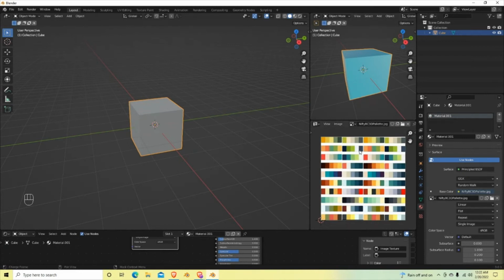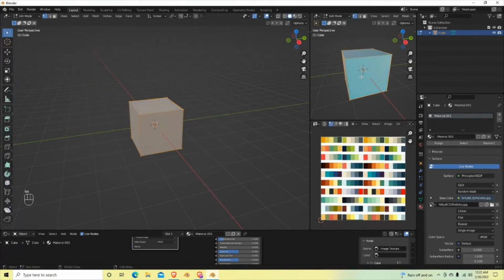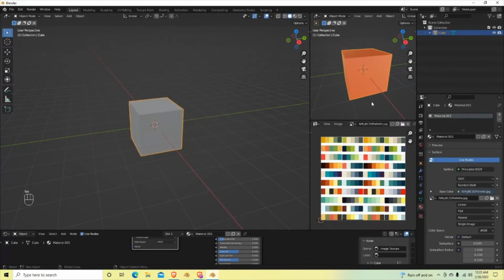This is how we want to change. So if you want to change the color, you notice how you can't see that yellow dot anymore down here. You would have to go into edit mode, which is Tab. You'll see those vertices kind of pop up. And now you can hit G and move this around to another color that you want. So let's say I want to make it red, and then hit Tab to get out, and there you go. You got a red cube.